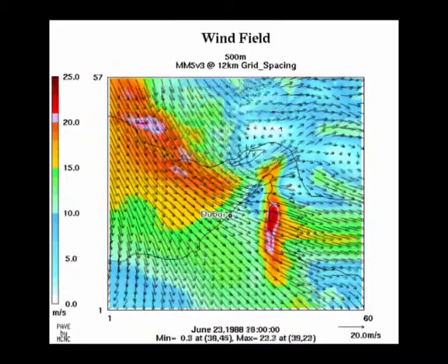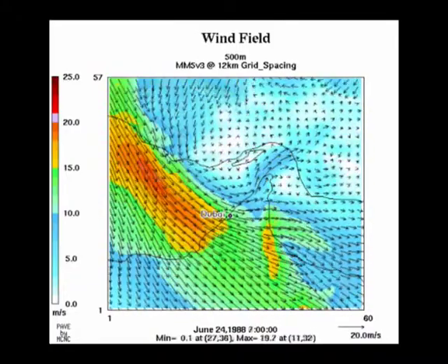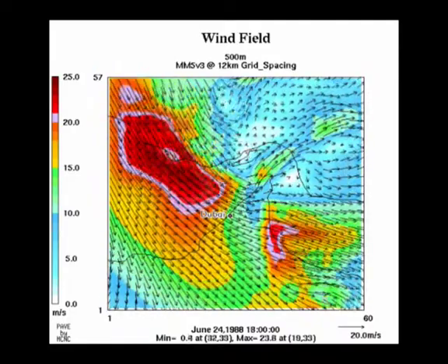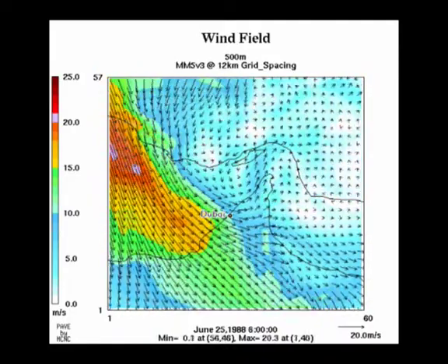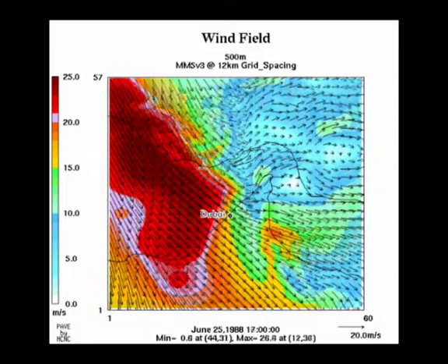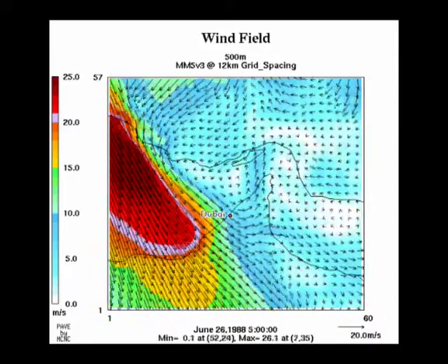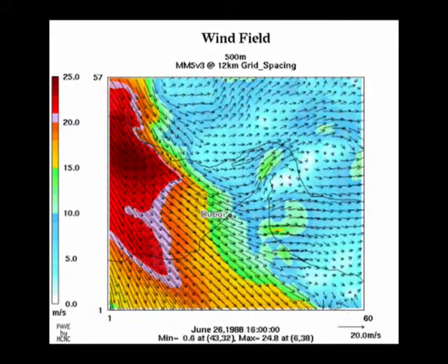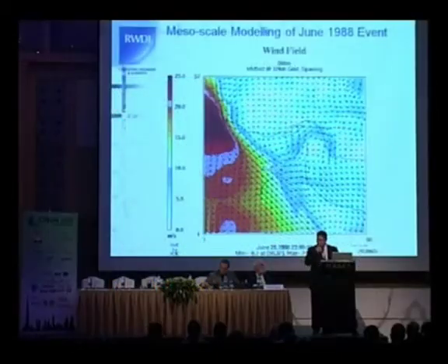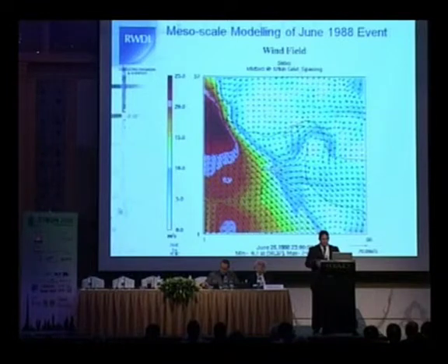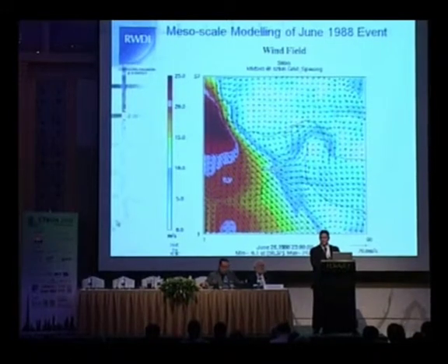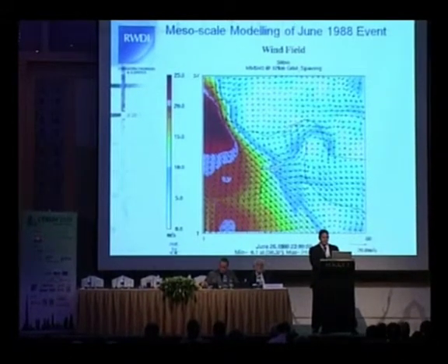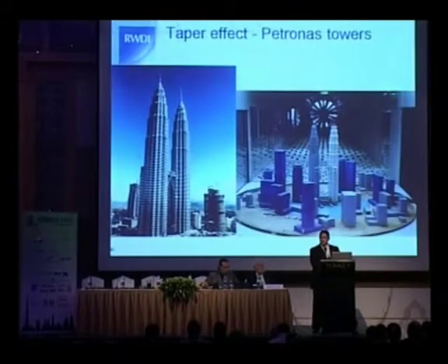One problem as we go super tall is there's very little information about the wind speeds and turbulence at high levels. This is an example of the wind climate over Dubai. That's one particular event in 1988, Shamal winds, and it basically shows how variable the winds are at that height. This type of study, the forecasting tools that we use, gives us an idea of the way velocity changes with height.